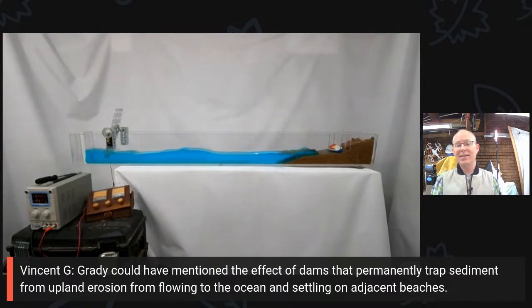So if you starve a river of its natural sediment load, all of a sudden it becomes much more erosive. This is something you see downstream of dams: once that sediment settles out, all of a sudden the water downstream is much more erosive, and the stream and the beaches are much more prone to erosion once the water is starved of its natural sediment supply.